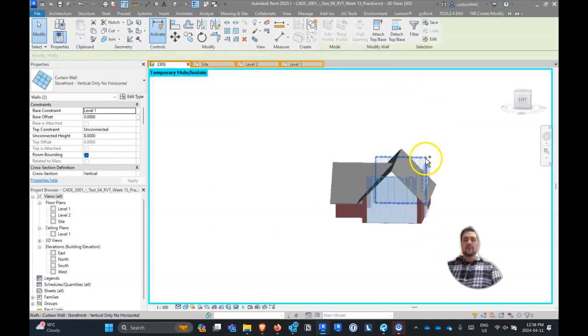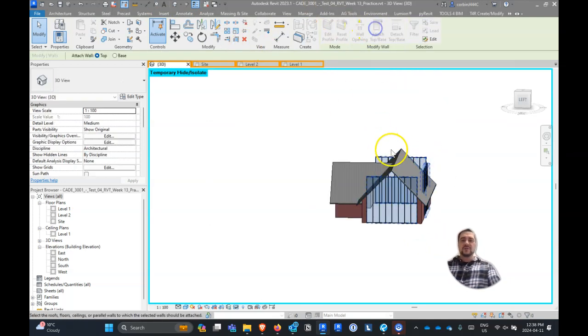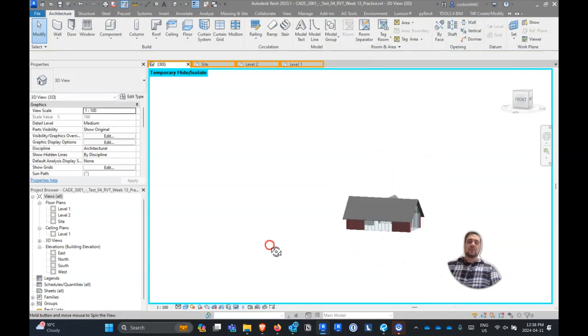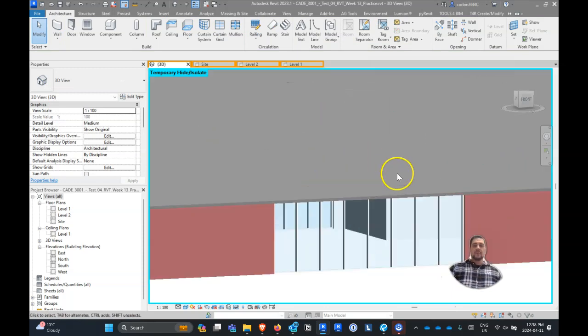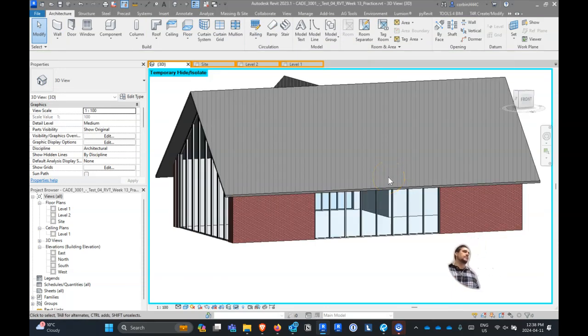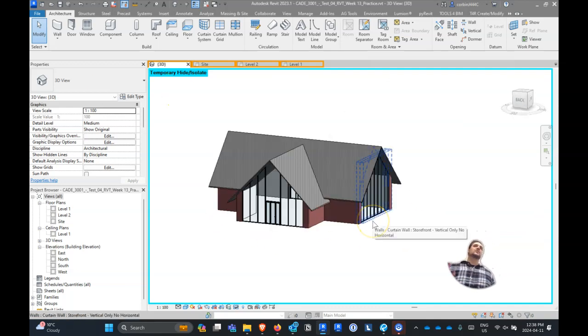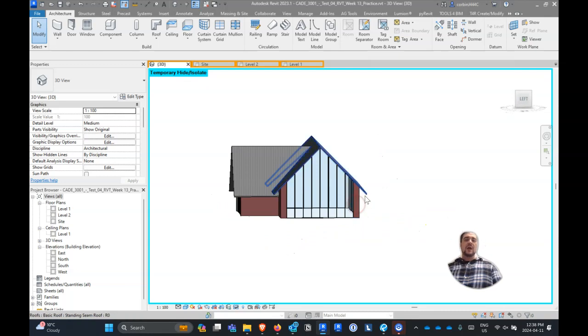So we have our 3 curtain walls here, and you could certainly download some sort of curtain wall panel system from that website and find something that maybe is a multi-panel thing that opens, and you can use this technique to have some control. Again, I use the vertical mullions only just to create that pattern, and then I switch it to no vertical, no horizontal, so then I can customize that pattern. I can move the mullions to wherever I want them. So anyways, we have this done.